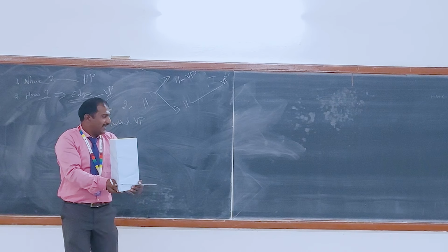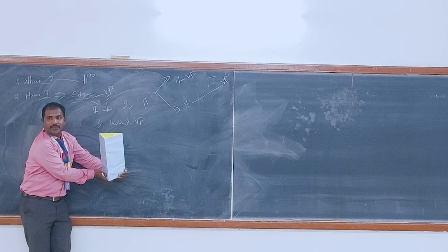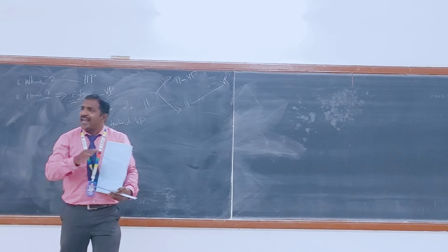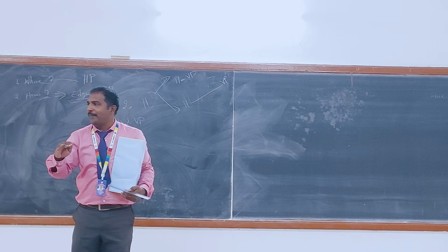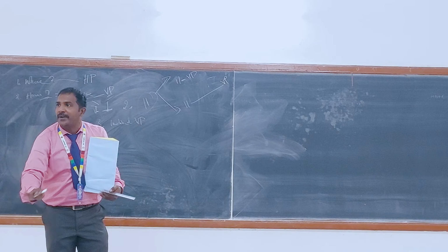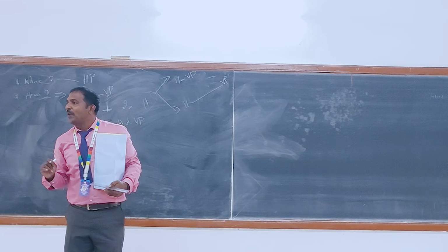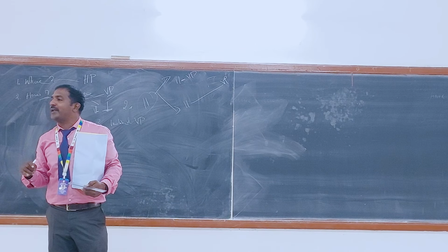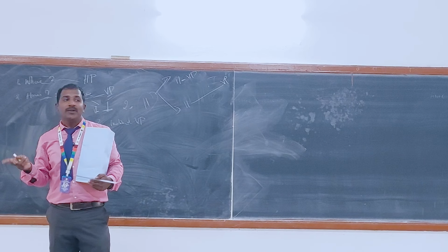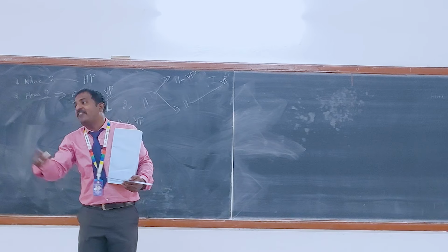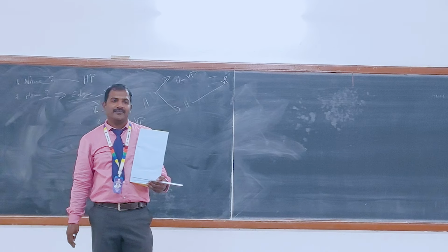The edge is inclined to VP. These are the conditions. A triangular prism of base side 30 mm, altitude 60 mm is resting on its base on HP such that one of its base edges is perpendicular to VP, or parallel to VP, or parallel nearer to VP, or parallel far away from VP, or inclined to VP. That's it. You can draw any diagram.